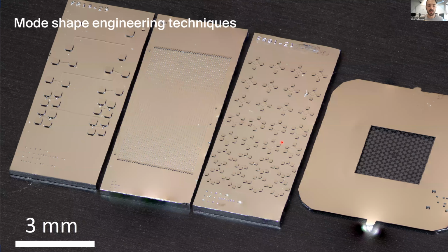So, okay, this basically concludes the first part, where I talked about this work on strained silicon mechanical oscillators. And then I will more briefly touch on some other techniques for improving the quality factor of mechanical resonators by playing on the dilution factor instead. So we introduce some more mode shaping engineering techniques that we have demonstrated typically in silicon nitride nanomechanical oscillators in our lab.